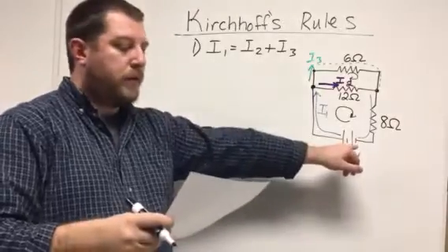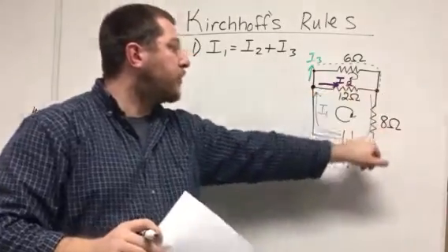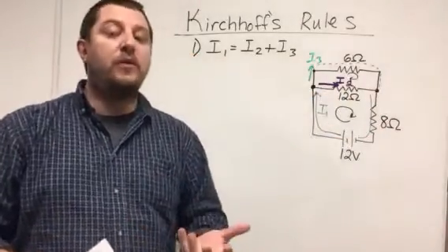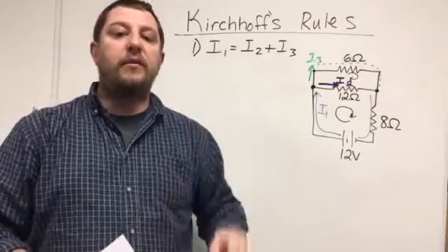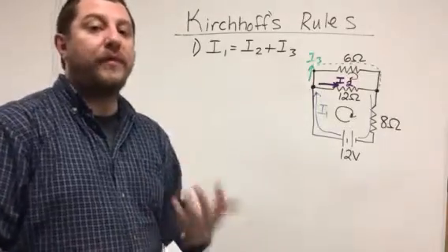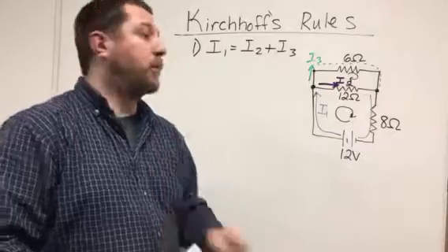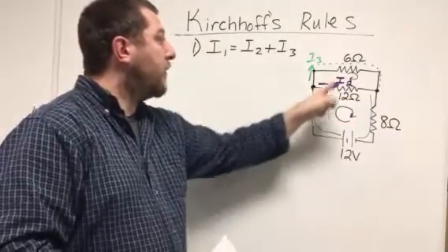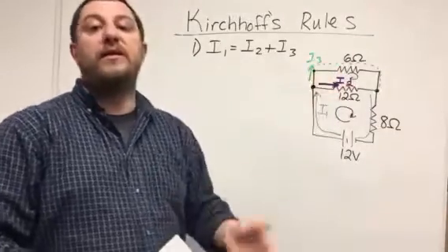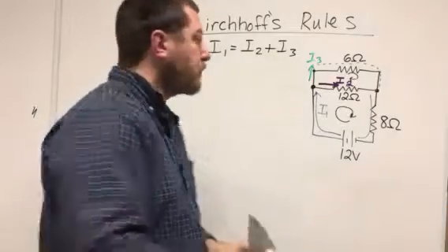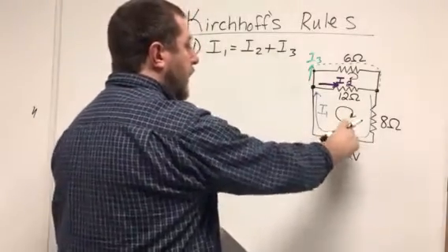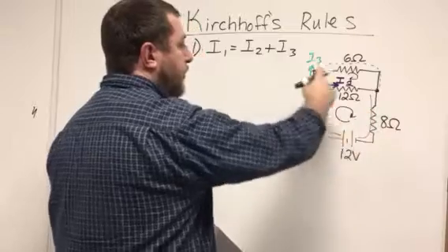Now, we want to use the loop right here, and again, you can use any loops that you want, okay? You are not restricted to the loops that I choose. You have 3 at your disposal, you just need to use 2 of them. I'm going to use this one, and I'm going to use this one, the 2 that I talked about in the previous video. So if we start here at the battery, and we go clockwise around the loop,